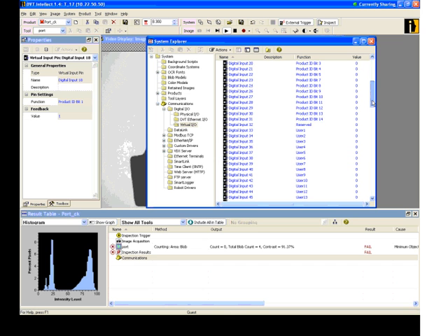And if we look down here below, we have user 1 inputs, and input 2 is low because I'm not physically bringing that high. And if we look at output user 1, remember I had that other one go high for us before when the gasket failed, but right now it is not going high at all because it is passing and I haven't assigned it anything.